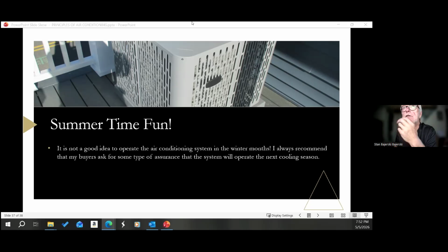So now you added extra living space. Or this could even be with heating too. They convert their basement and they add heat to it. If that system wasn't sized for that extra square footage, let's say it pre-existed, who knows how evenly you're gonna heat the house, right? Because you've added, it's gonna run longer to get to the temperature.